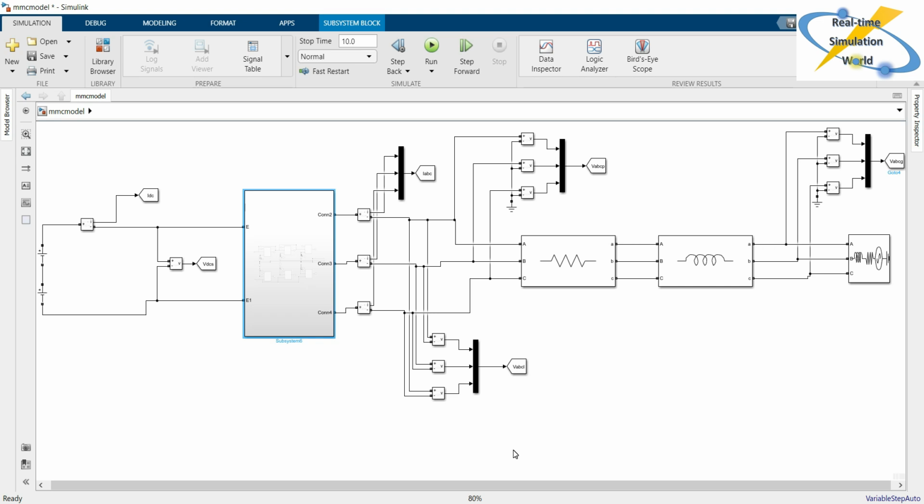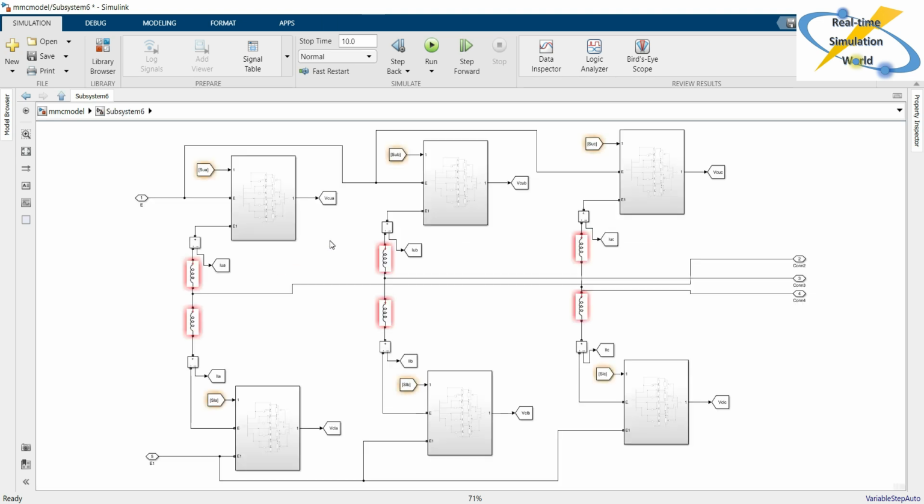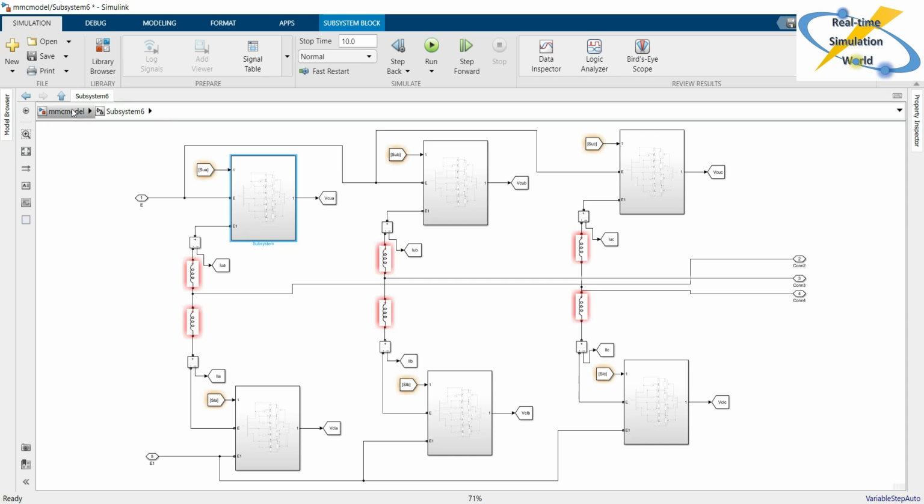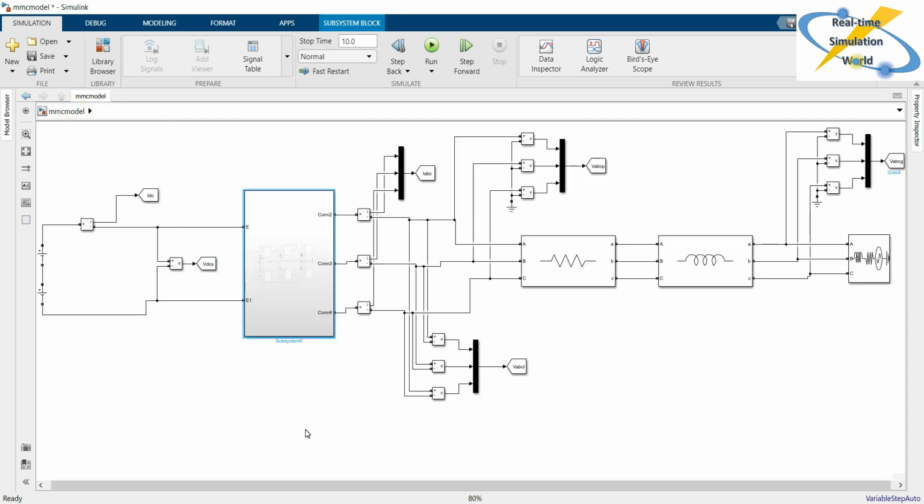Now in closed loop control, we have to use the system parameters, and using those system parameters we have to control our inverter in such a way that it ties with the grid, and more important, we have to control these capacitors so that they charge and discharge, and they work in a way that the voltage, or the active and the reactive power, are controlled.